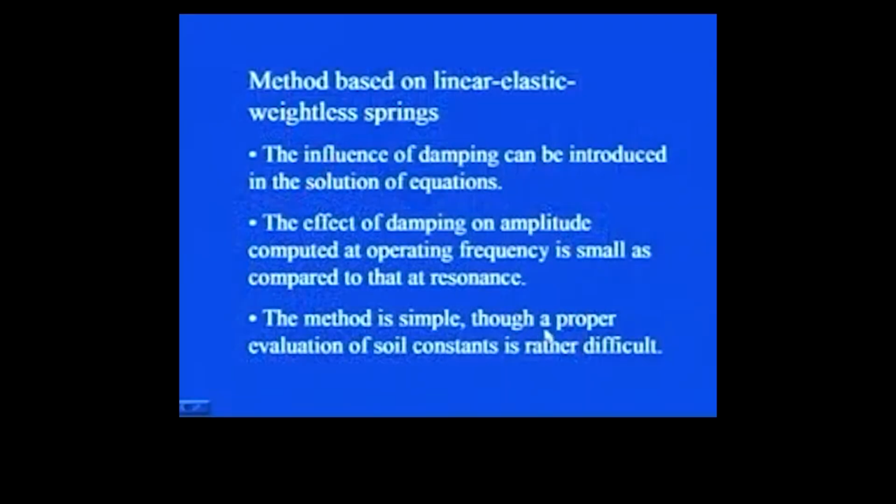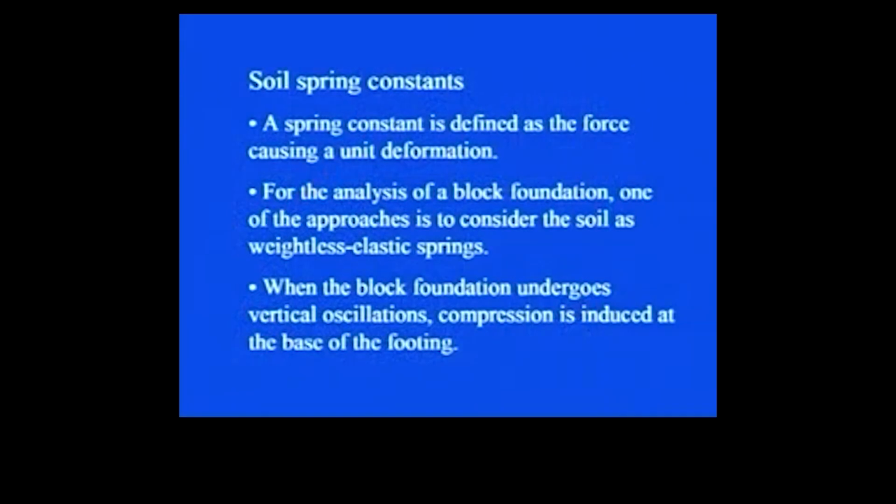The method is simple, though a proper evaluation of soil constants is rather difficult, since you are replacing the soil by equivalent springs. You need to know the characteristics of that particular soil so that the modeling can be done properly, and evaluating these soil constants is quite difficult. We have different measures. So let us see what the different soil constants are and how we can obtain them. First, soil spring constants.